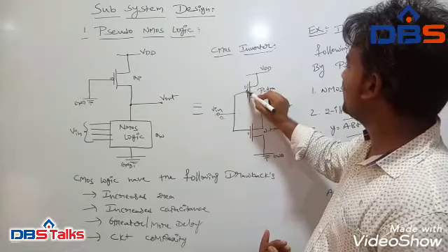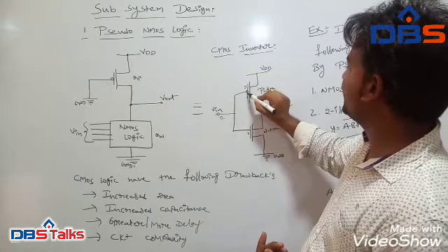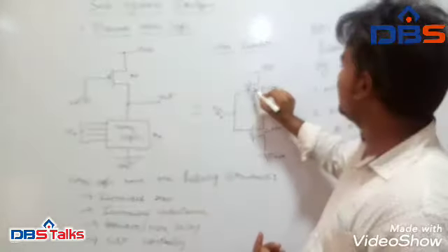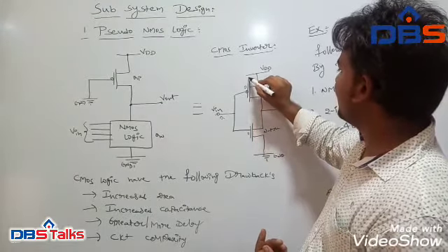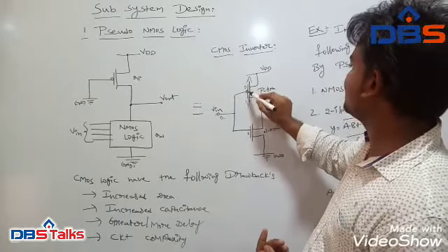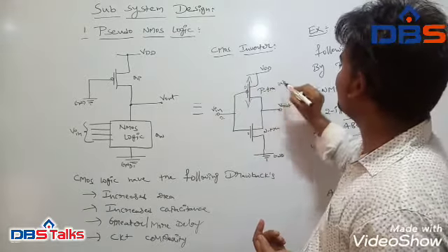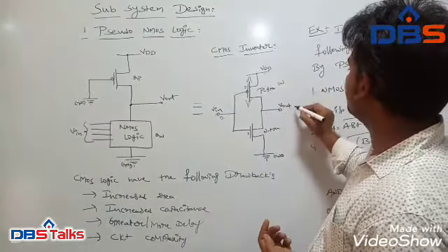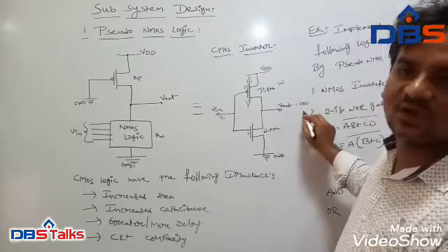Due to the bubble at the gate, the channel between the source and drain terminals will be established, creating a connecting path in the P-type transistor, so this transistor will be on. On means it will be connected to VDD, then the output voltage is equal to VDD.